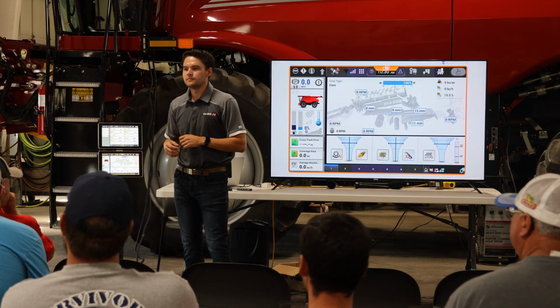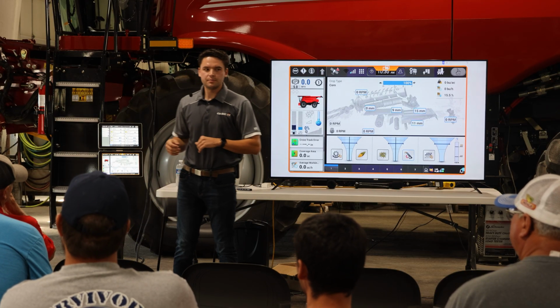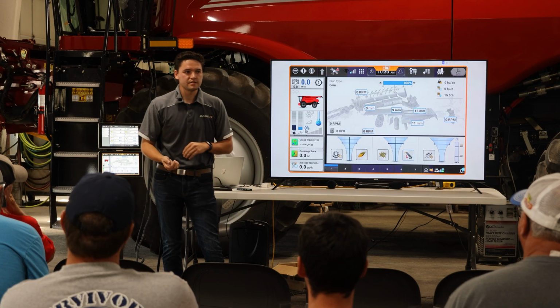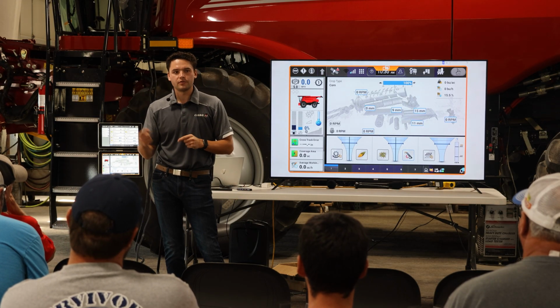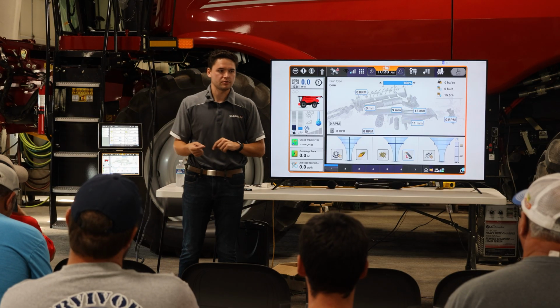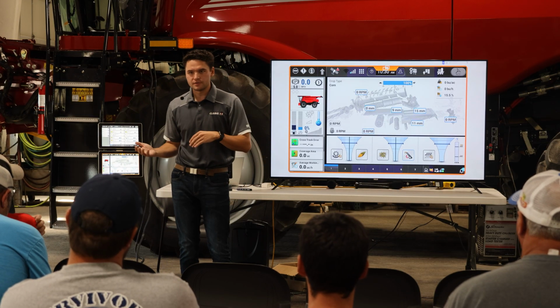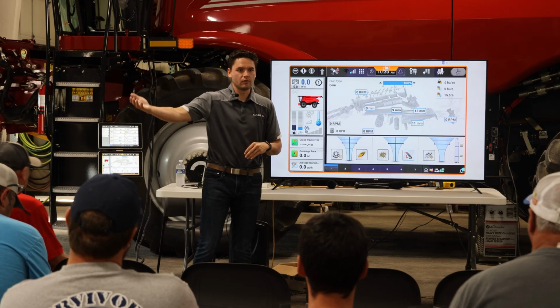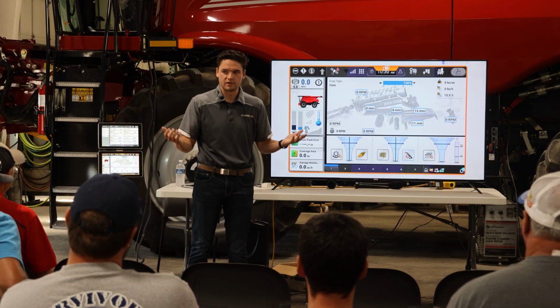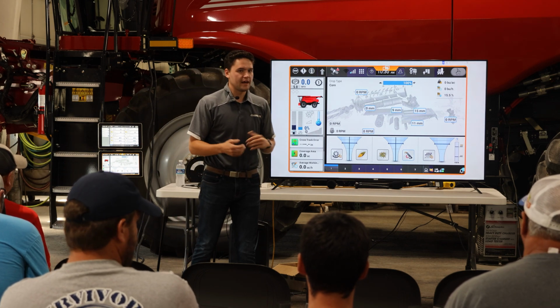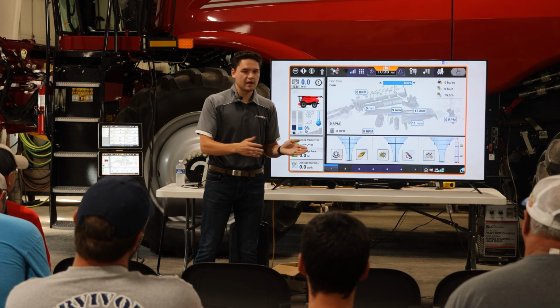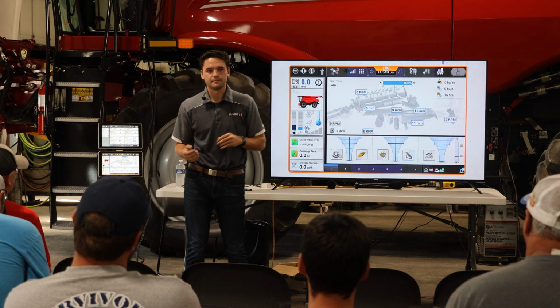If you're going to do an offset, how big is an offset? Typically speaking, when we're doing these offsets, let's say we go back to that 10 and that 3, I like to do it at 0.1 of a degree at a time, maybe 0.2 if it's extreme, because we don't want to overdo the offset, because then all we're doing is transferring the problem of overloading the right to the left side and vice versa. So typically I like to do small increments at a time. That way we can get it the first try and then we don't overcorrect and have to come back.